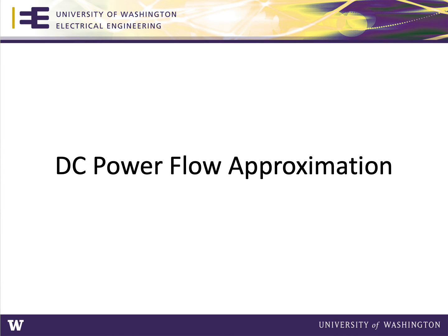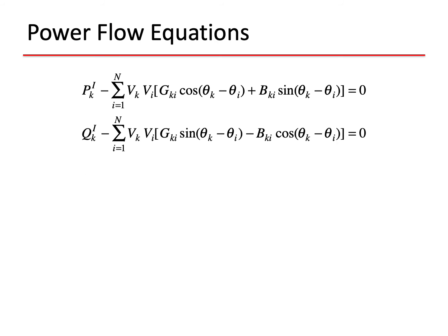In this course, we will make extensive use of the LP-based OPF, and therefore we need to understand the linearization. The first step is to study the DC power flow approximation. We'll start from the full AC power flow equations.